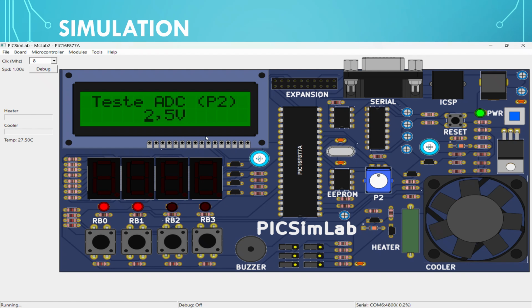After a fixed delay, the cooler and buzzer turn off. The LCD updates to show this, which is done to provide user feedback. In real-world embedded systems, visual confirmation is essential so the user understands the current operation mode without guessing. So this at present shows the current temperature. Now the heater is high.